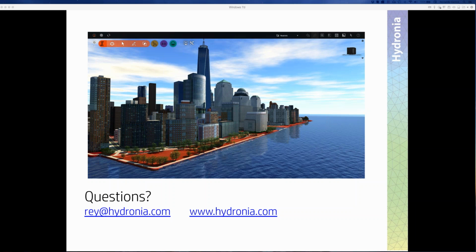And so what you can do in SMS is, for instance, define a polygon that covers all the riverine area, and you can use a different data set on that polygon that covers the river, and then use the LiDAR data set on the floodplain, all the coastal environment.